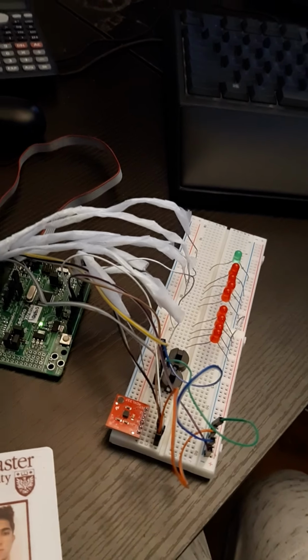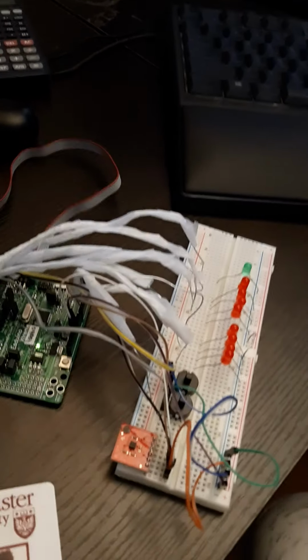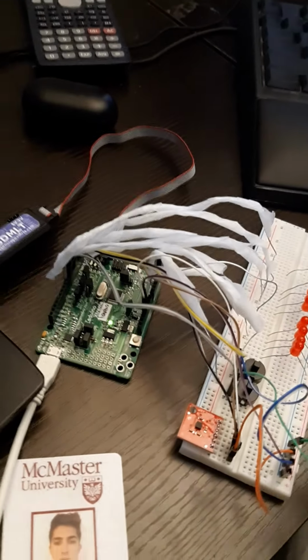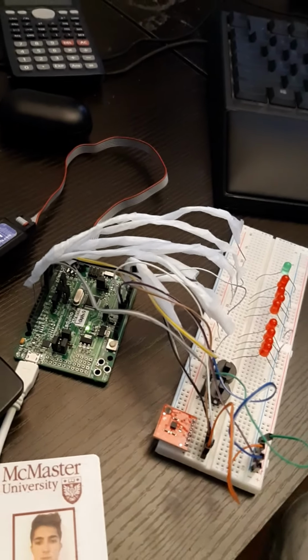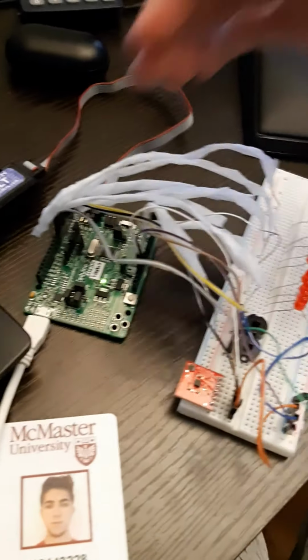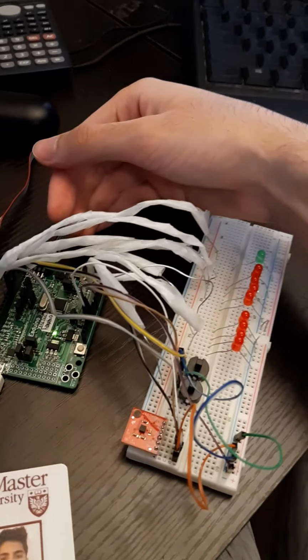A transducer is a device that converts a physical phenomenon into a voltage signal. In this lab, that will convert the static acceleration of gravity into a voltage signal, which will then be sampled through the Arduino. That sample value will be used to calculate the angle of inclination using linear approximation.